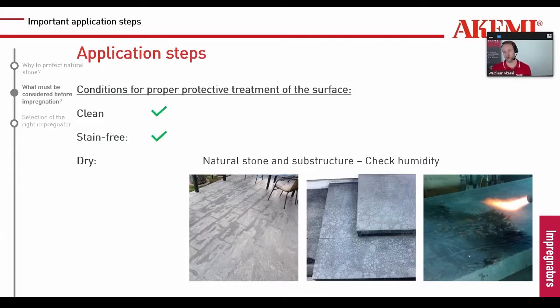A second thing is to have the weather in mind when it comes to outdoor treatment. If you know in the afternoon there will be rain, you should not apply impregnation in the morning, because usually they need 24 hours to fully cure, and when they are not cured and it starts to rain, something like this can happen, as in the middle picture. So you have to be aware of that.